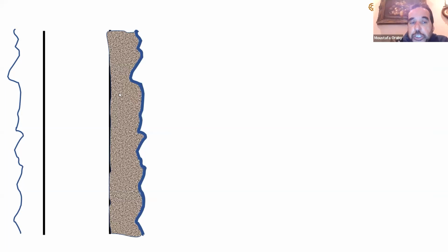Here is a situation where the cement is in a very good condition. I put the cement here. It's in good contact with the casing, and in good contact with the formation. This is one case that we all like to have. I'm looking at half of the wellbore; the other half should be the same. I'm just putting one half here. Don't say that I'm cementing only one half and the other half is not.